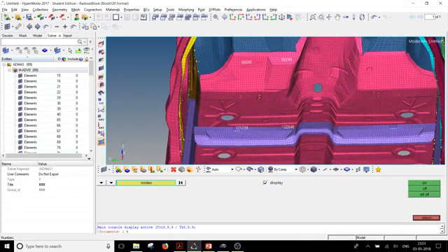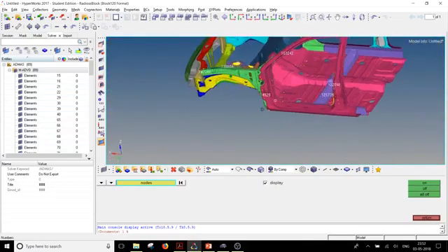So you'll create a spring between these two nodes. The only trick here is that the stiffness of the spring should be very small. So 0.001 kilonewton per mm. That is still 1 Newton per mm, and that is still a good stiffness. So maybe 1e-4, 1e-5, that can be somewhat acceptable stiffness. It should not make any difference to the physicality of the problem, and that is why the stiffness should be very low.